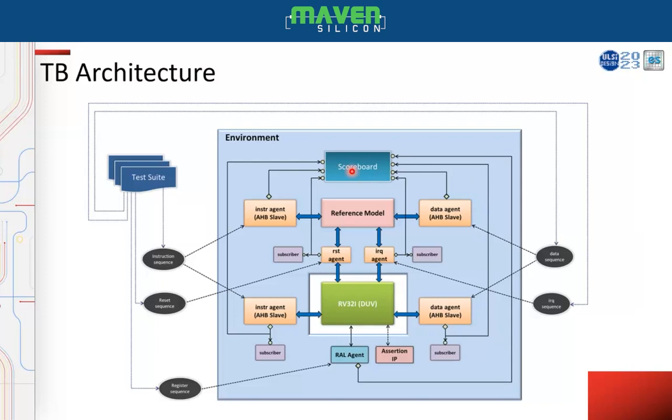And of course, validation is not possible from the reference model every time. For example, during the execution of an arithmetic instruction, our processor will not produce any output through the data output lines. The data output lines will produce outputs only during the execution of memory instructions like load and store.